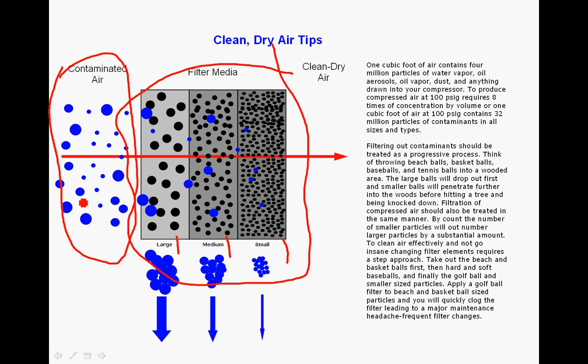And in many cases, the most efficient way to filter, if you've got a wide range of things to clean up in your compressed air before you actually utilize it in your facility, is you probably want to go to multi-stage filtration, and that's a whole discussion topic on its own, but keep this concept in mind.